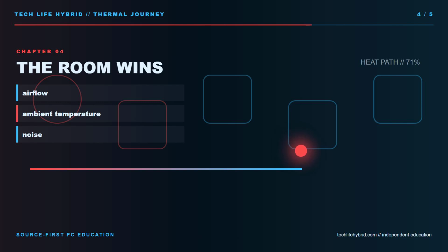The thermal journey ends in the room: silicon, interface, cooler, fins or radiator, case airflow, then ambient air. Follow that chain and cooling becomes understandable. Measure the full behavior, fix the weak handoff, and aim for stable performance at noise you can accept. That is cooling that makes sense.